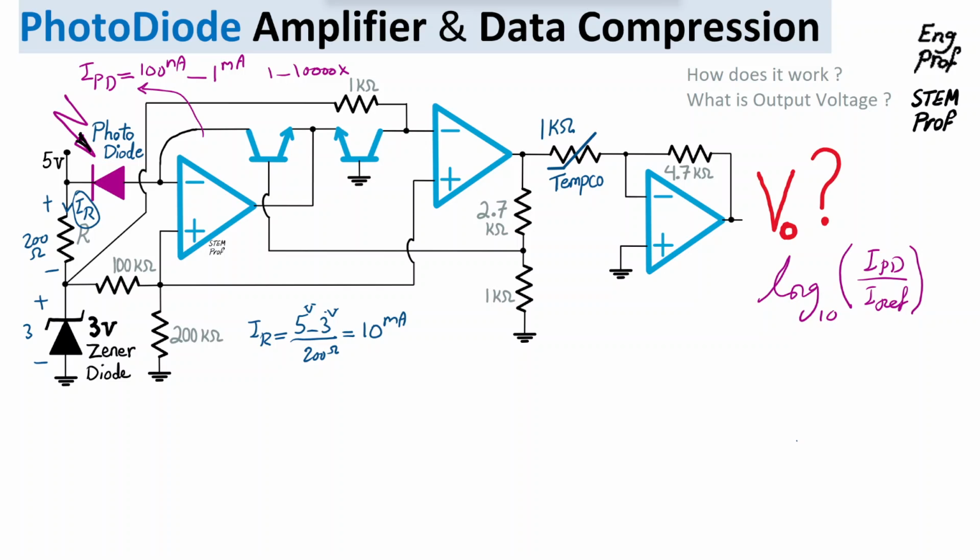And when we have 3 volt, that means we effectively have a series of 100K and 200K here, because this branch gets to the positive terminal of ideal op amps, which do not take any current. So we know that this route and this route are not taking any current. As a result, the current here is roughly on the order of just 10 nanoamp or so, very small currents, basically close to 0.